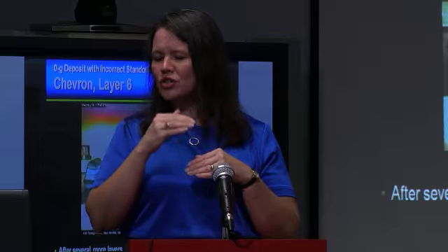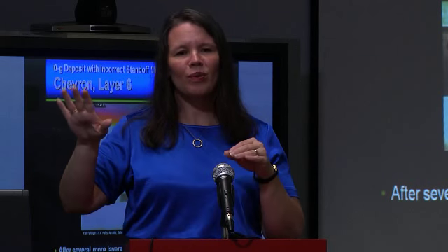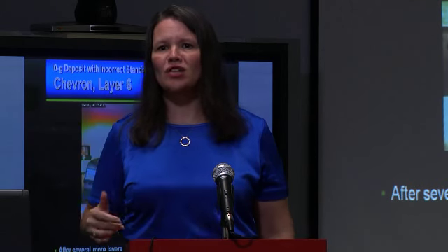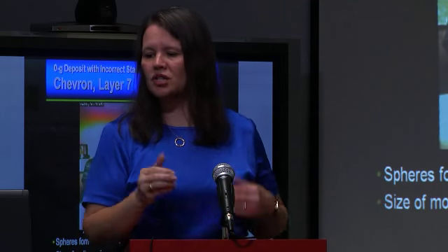And the errors become cumulative. So they get worse and worse. On the ground, it would just drip, very regular pattern, and you can recover from that. In 0G, there's nothing that shakes that drip loose from the end of the wire. And so it just keeps getting bigger until we make contact.